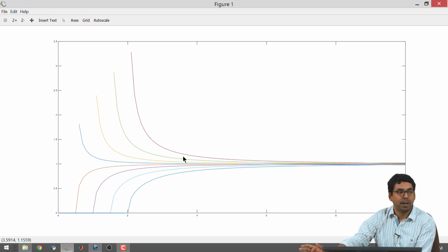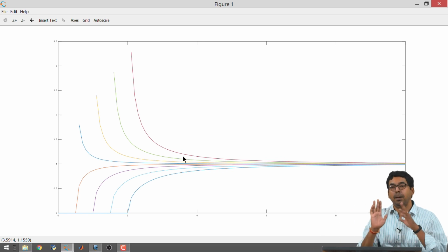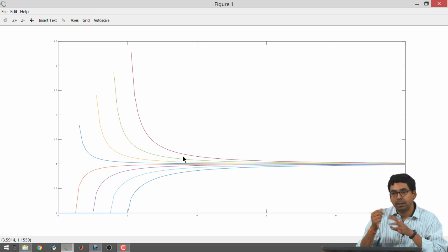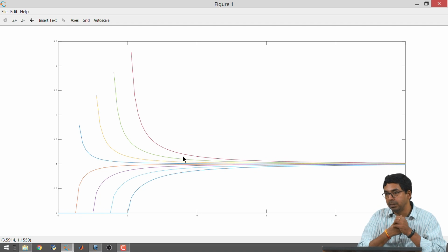So, you have kept the f cutoff fixed, that means for a given mode the configuration of your parallel plate is fixed, D is fixed, the medium filling it is fixed, but just with respect to frequency you are having different group and different phase velocities. There is only one more detail that we have to add over here.